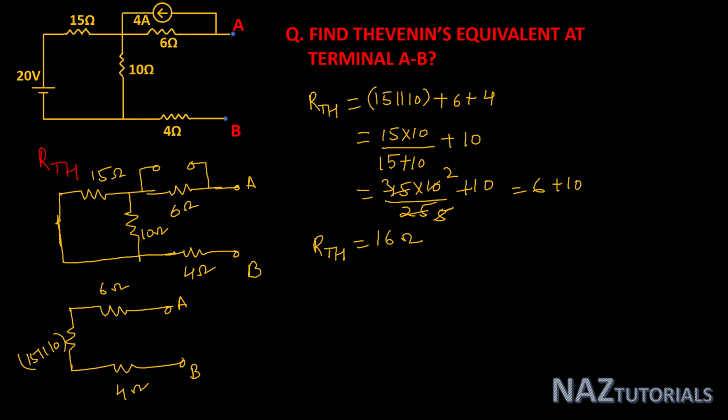So here we calculated VTh and RTh. Now let's see the Thevenin's equivalent. If you see, it is a Thevenin's voltage in series with Thevenin's resistance RTh.